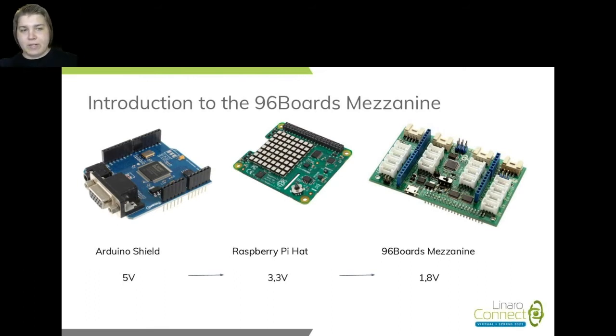This is due to the fact that 96Boards is a platform for software development and hardware development on mobile system on chips, and modern SoCs don't support these logic levels anymore. That's why we have this 1.8-volt logic level. It isn't as friendly to the normal beginner as the other two platforms.